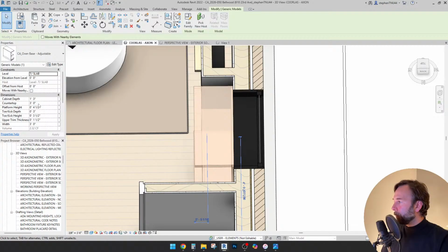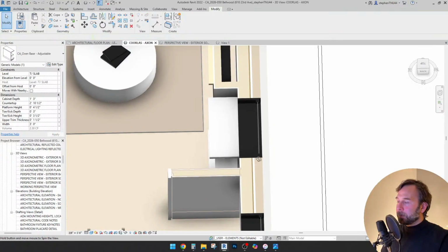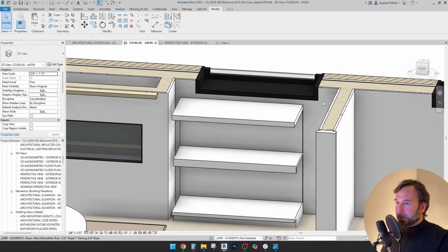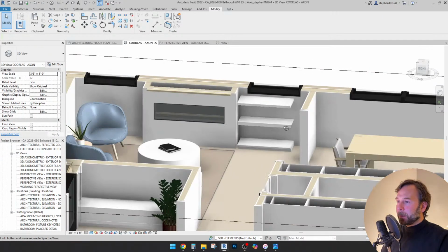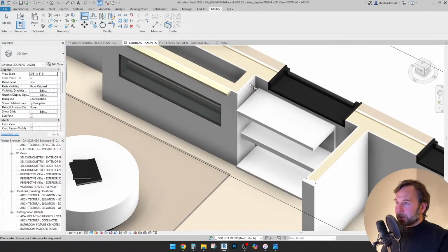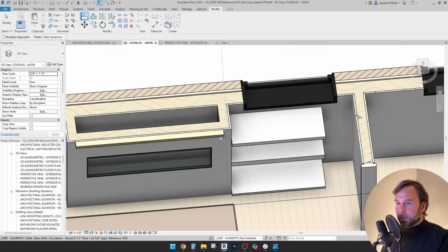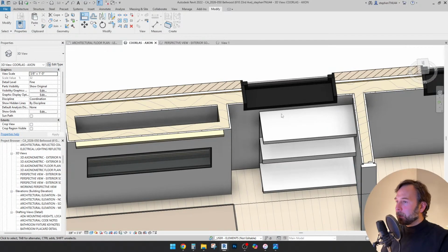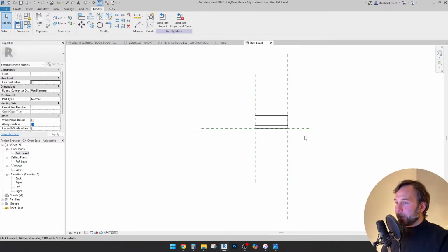So now we're all good, and that's the actual depth that I wanted. I wanted the 1'3" on this. The countertop will return to the 2'10.5". So I know when I add my countertop, it's going to come to the underside of that windowsill there. And then let's see if we can just use these align tools to... No, we've got to edit that also.